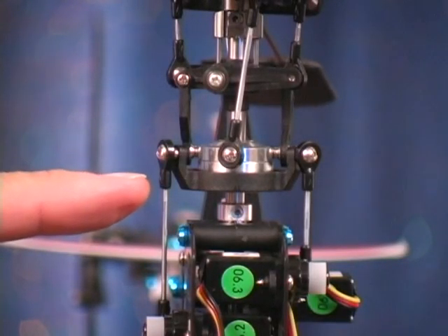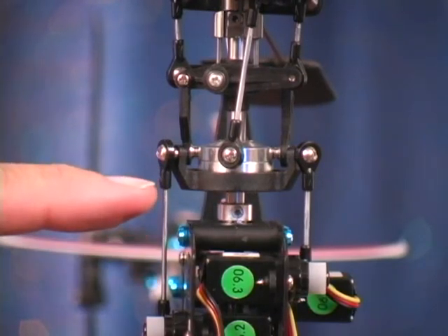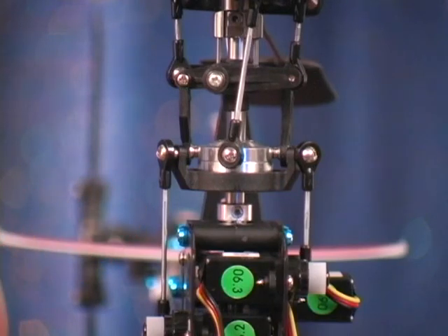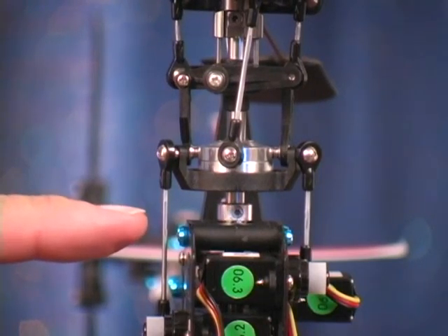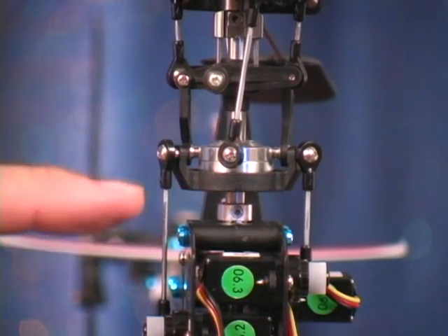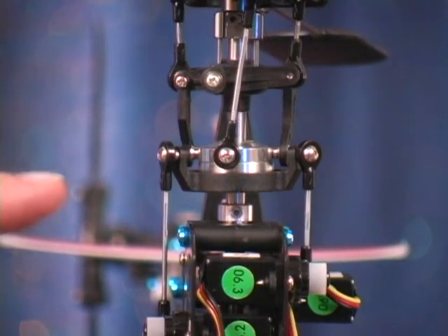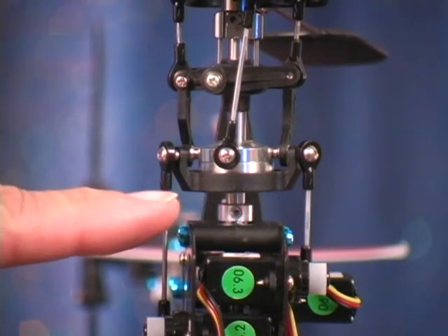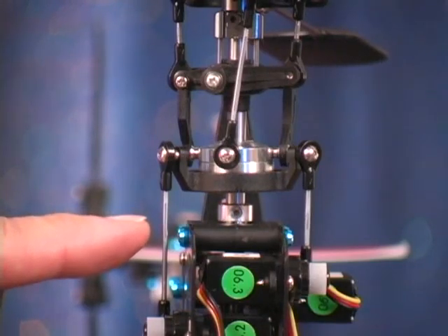Here's a head-on view of the swash plate, and now I want to physically adjust the length of the push rods so that the swash plate is tilted just barely perceptibly to the right, about like that. Basically, I'll start out by shortening this one full turn and lengthening this push rod 1 full turn. Here's a 1 turn adjustment in each push rod. We've got a barely perceptible right tilt in the swash plate, and when we hover the helicopter, if it needs any right or left cyclic trim, we'll do that by adjusting these 2 push rods.